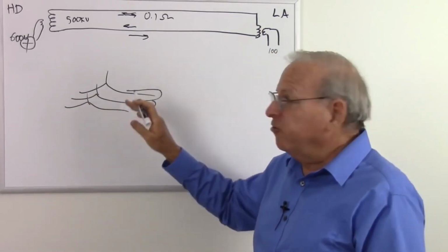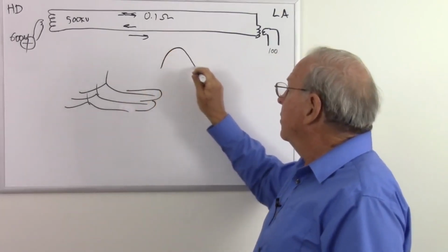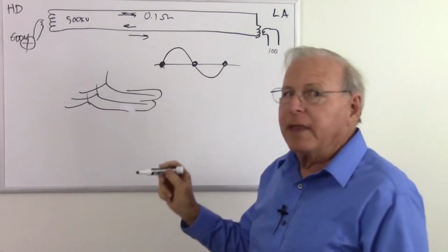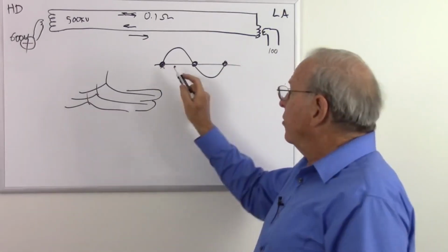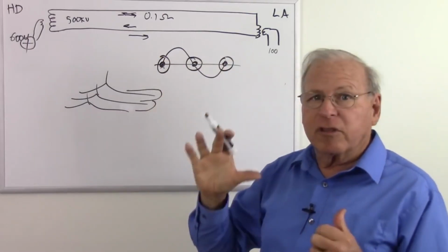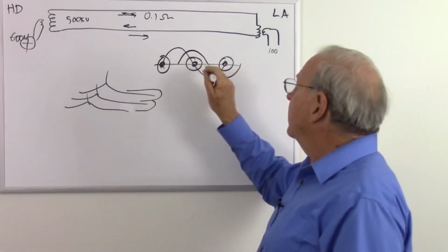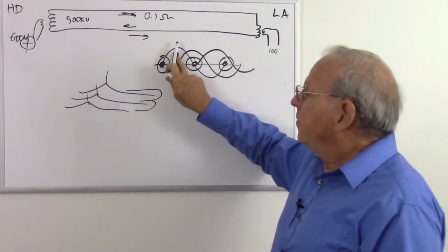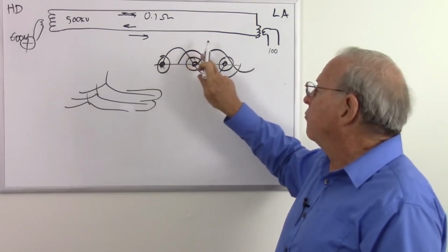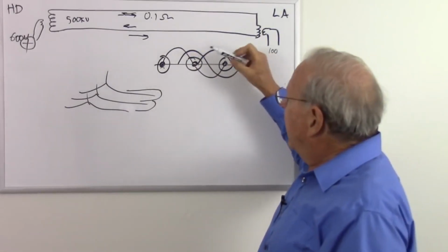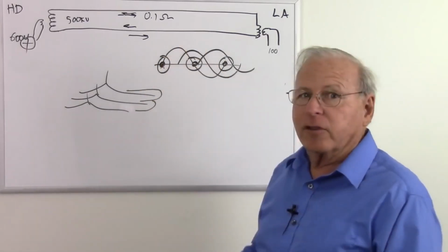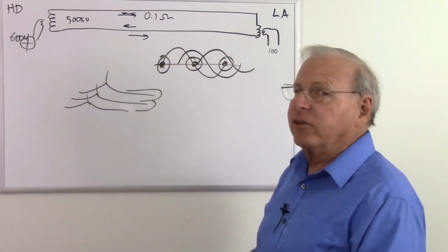Now the other reason is, as I mentioned, is that with a single phase, there's a lot of time where we are near or at 0 volts. And so if we have a motor that runs on single phase, well, it's not going to be producing any power during these times. So if we have a motor that's designed to work on all 3 phases, then when it's losing power from this phase, it's starting to get power from this phase. When this phase starts to drop down, it starts to get power from this phase. And so these all work together so that the power in the motor is evenly distributed across the 3 phases, and it doesn't have any time that it's not actually producing power.